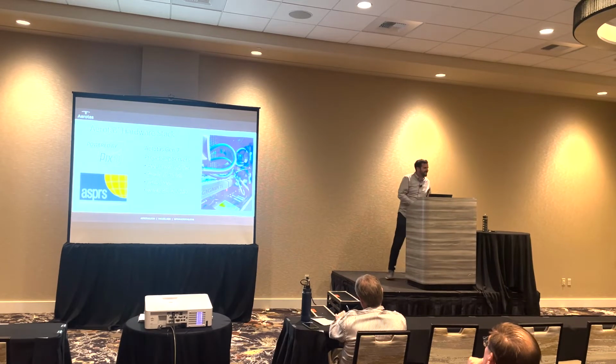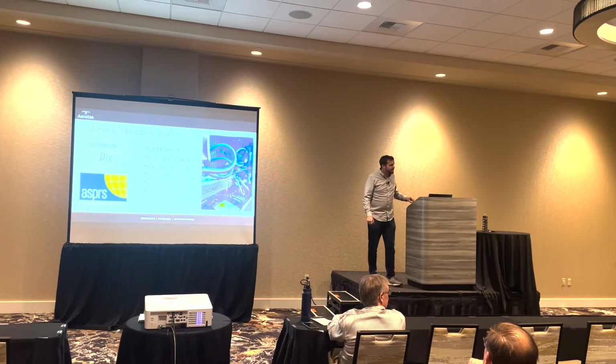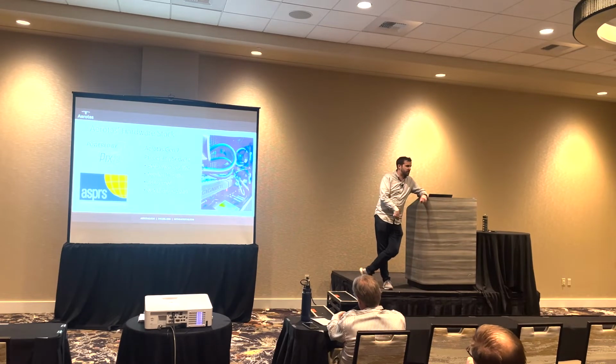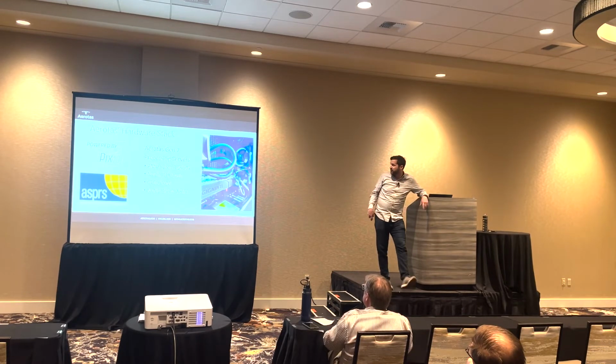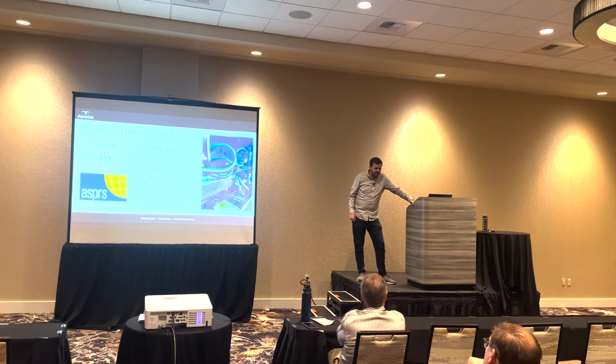There was another question. I was just curious, what component is typically the choke point on those computers? Great question. For photogrammetry and Lidar, it's different. I've actually got another slide of this specifically for Lidar processing. For photogrammetry, it's going to be 2 things. One is going to be the CPU. In this case, that's going to be the Ryzen 9 5950X. It's a multi-core processor. Photogrammetry is, generally speaking, a CPU-bound process. That's going to be number 1.